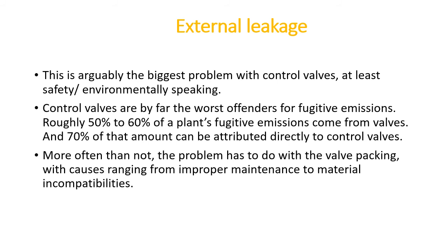More often than not, the problem has to do with the valve packing. The causes range from improper maintenance to material incompatibilities. It has been seen that the wrong packing has been used, or the temperature is far more than the tolerable limit of the packing. So this is again the design point of view. If the design is correct, this type of situation does not arise.